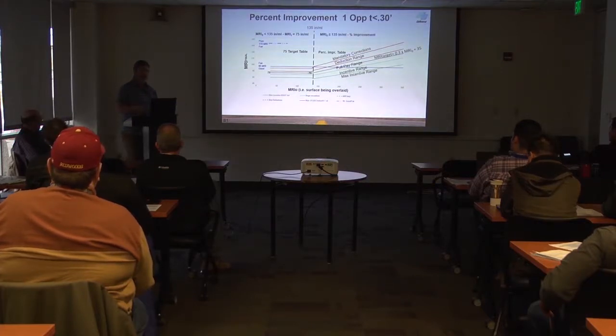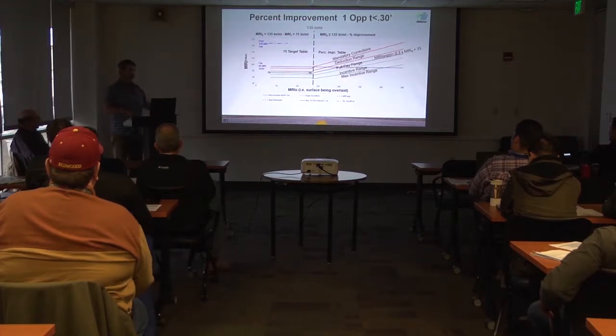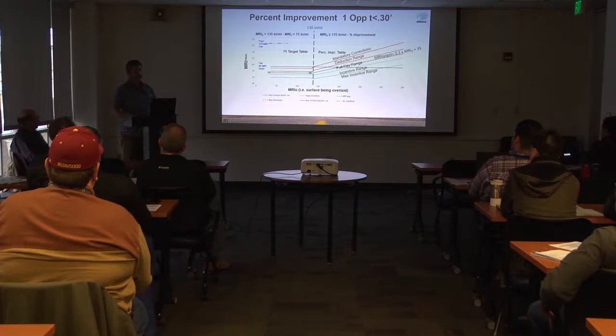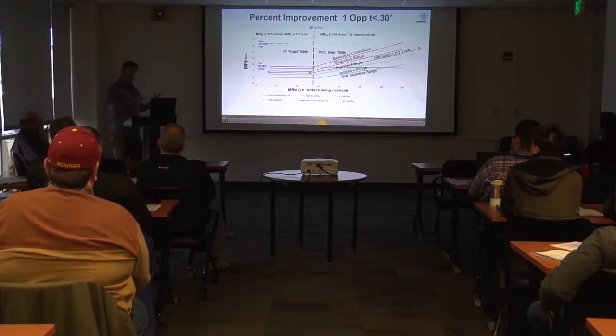Everything is getting measured now. In the past, it typically wasn't. In the past, you'd have an RE on one job where they paved at 80, and that RE says the spec says 75, they can't accept it. They go out there and grind, and they finish grinding all those 80s down to 75s, the whole job is ground up. You get to the next job and the RE kind of felt sorry for them and didn't enforce the spec. We have to be consistent throughout the state. So these new specs are going to improve that.